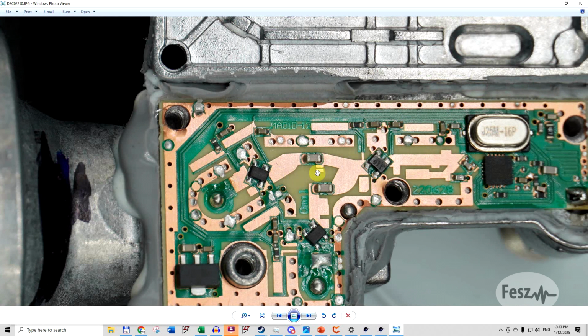Finally, a special case of the stepped impedance transformer to consider today appears in microwave applications, where the individual quarter wavelength sections become relatively short, comparable in fact to the width of the trace. At this point, adding, say, more than 10 sections is no longer that big of an issue. Here, you will find that the transition from one impedance to another is sometimes implemented as a smooth rather than a step structure. This can be visible in multiple points on this specific design.